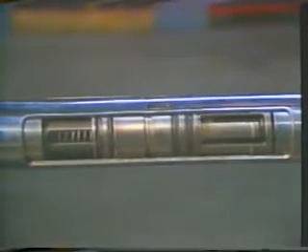Another wireline-operated component similar to a side pocket mandrel is the sliding sleeve or sliding side door, by far the most popular and widely used tubing casing communication device. The sleeve is run as an integral part of the tubing string and has an inner sleeve which, when positioned so that the slots of the inner sleeve align with the ports of the housing, will allow communication between the tubing and the casing. The inner sleeve is moved using a wireline-operated shifting tool.